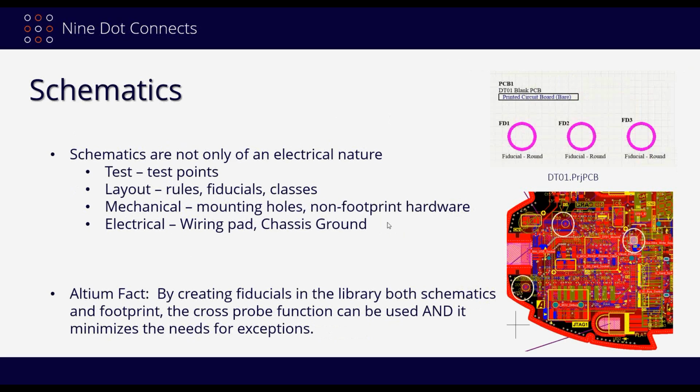The second feature is that Altium tries to stay lockstep with its net list between the schematic and the PCB. And if I just put things on the PCB without it being represented in the schematic, Altium's going to remedy that by trying to remove it from the PCB. And the only way you can remedy that is to either actually have a representation on the schematic itself, so the footprint and the symbol have correspondence, or you go into what they call project options and turn off capabilities so that it doesn't try to compare those things. But it's just better to keep things in lockstep than to have to try to make exceptions.